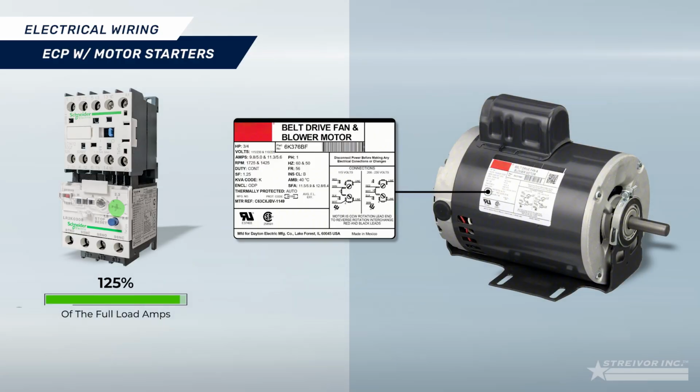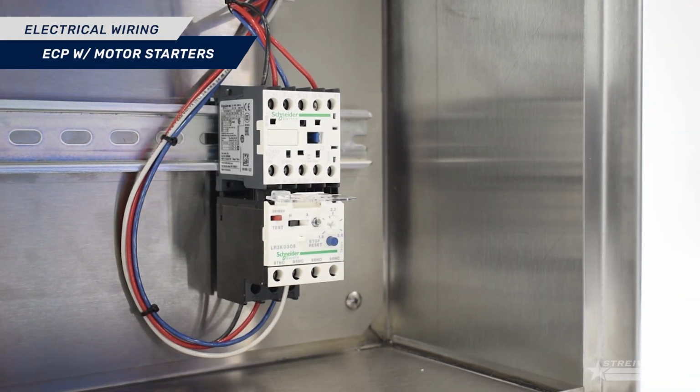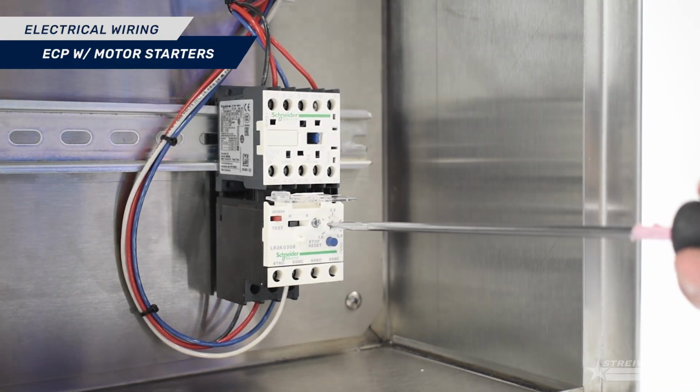Verify that each overload has been set to 125% of the full load amps displayed on the corresponding motor nameplate. The overload setting can be adjusted as needed by rotating the dial to the desired amperage value.